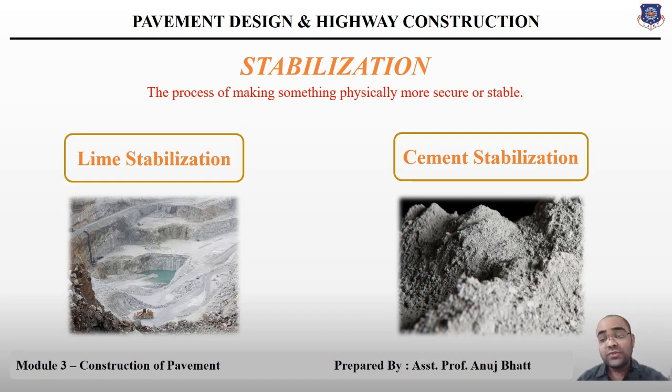Now the main use has been to build a stabilized base course under a concrete pavement for highways and airfields. This can be asked in an MCQ, that cement stabilization can be particularly provided at highways and airfields. Airfields, like if you want to construct a runway, at that moment you can apply cement stabilization.